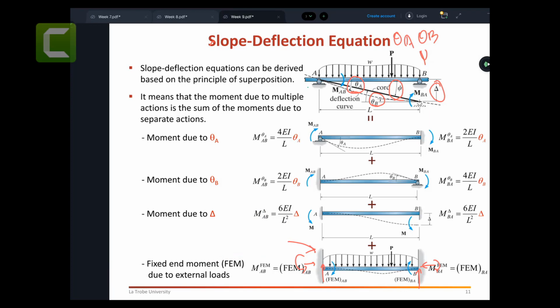So what I want from here to here is to make the structure kinematically determinate first. Initially it was kinematically indeterminate by degree 3: you can see theta A, theta B, and psi. So what I did, I come here and put two big clamps, meaning holders. I put the clamp on the beam and make that fixed. So when I make this clamp, it becomes a kinematically determinate structure.